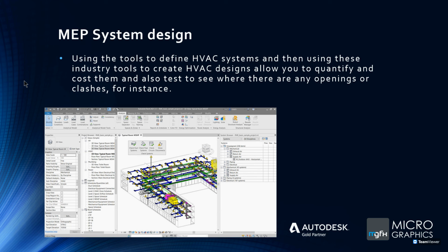You need to then make sure that all the unassigned objects that are floating or not part of your project or systems are assigned to a system. Once that's done, if you look at the little image there, there's an area that's called unassigned. If that is 0, you know that all your HVAC components or MEP components are assigned to a system. They are costed and relevant. Otherwise, they're just floating and it's not actually relevant.